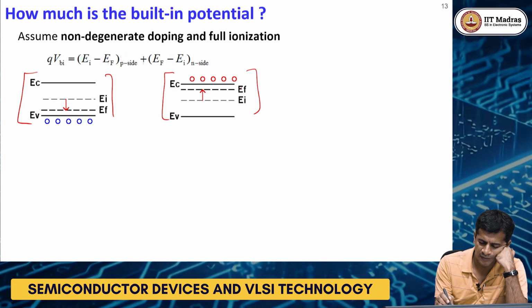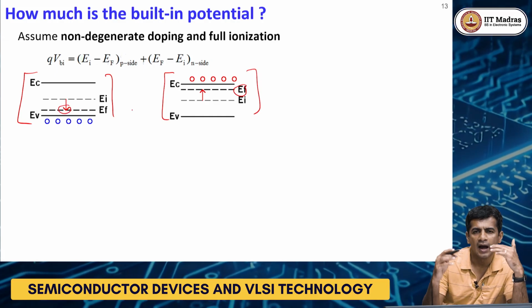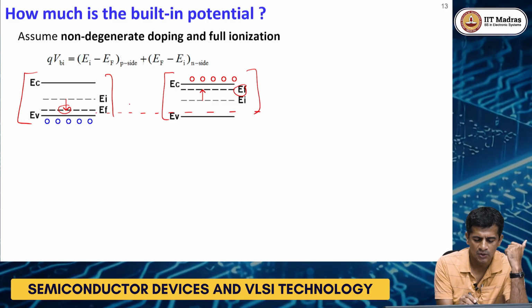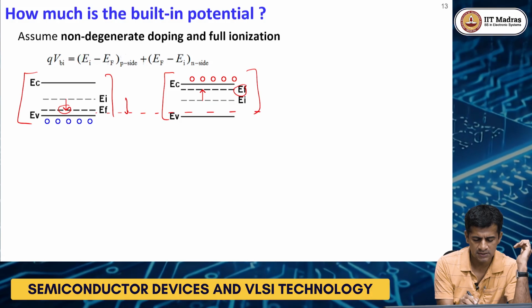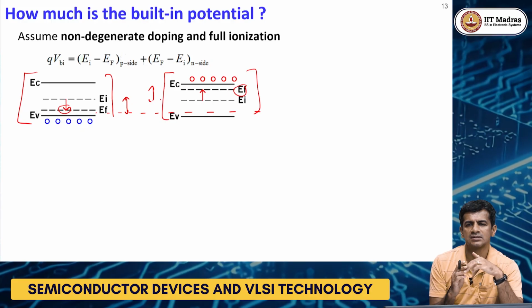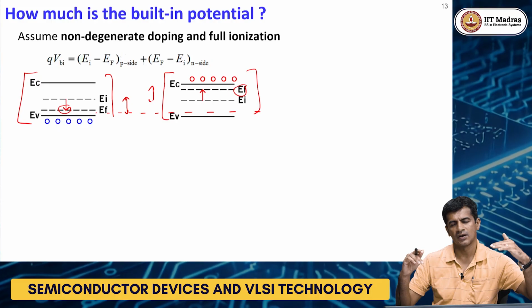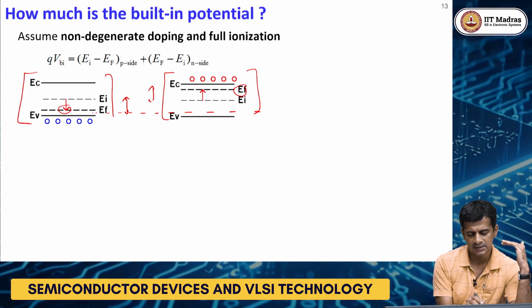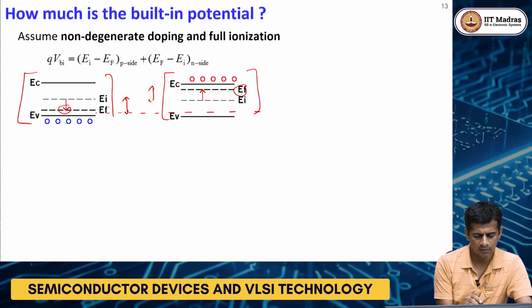Earlier the Fermi level was here, and this Fermi level was here. So at equilibrium the Fermi levels should balance each other. Essentially the amount of band bending required is nothing but this distance added to this distance. If you keep one side fixed, the other side should shift by that amount to have the Fermi levels aligned. So what is this distance?